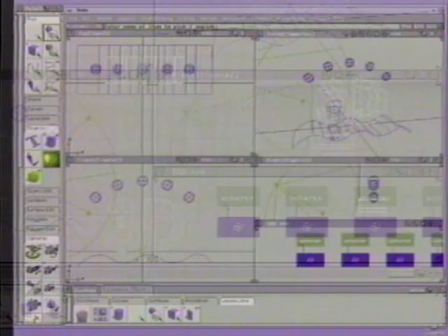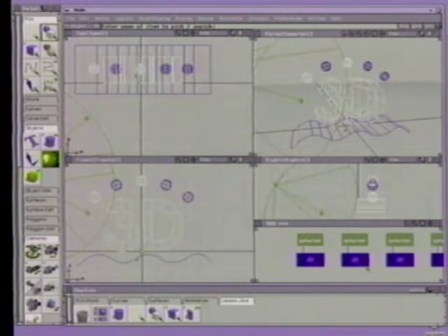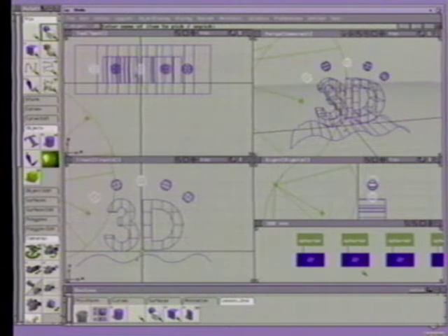With pick object still selected, click drag a pick box around 2 of the sphere nodes with the left mouse button. In the modeling views, the spheres and the 3D text are now picked. This time, click drag a pick box around the 2 sphere nodes with the middle mouse button. The 2 objects are picked and the text is unpicked.